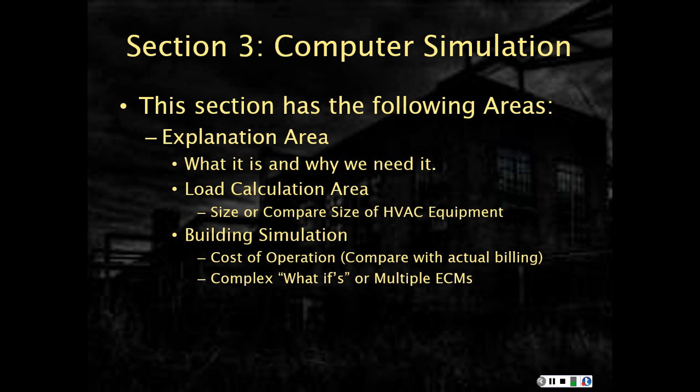In this case, we know if something's oversized, undersized, is there a problem there? Frequently, oversized equipment has trouble with short cycling, a lot of increased maintenance. Undersized equipment runs all the time, and there's still comfort issues in the space.